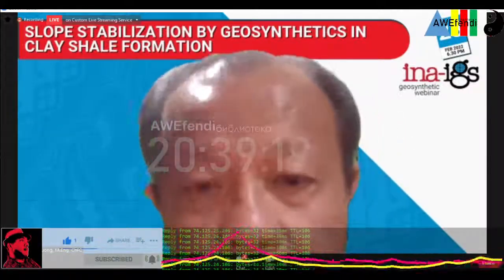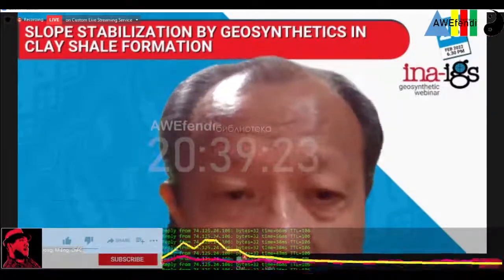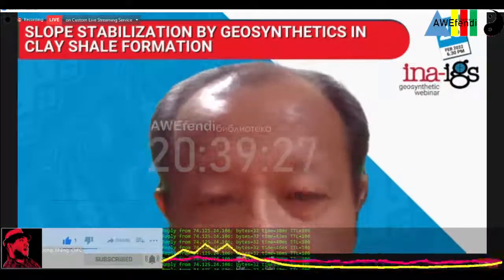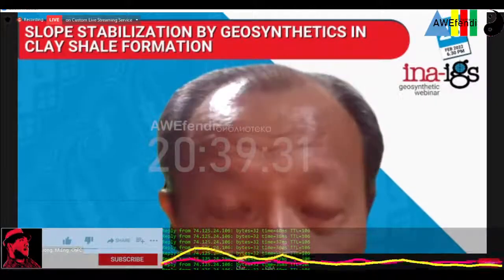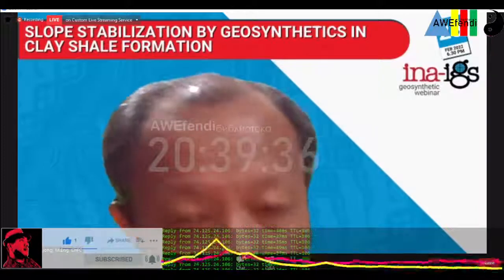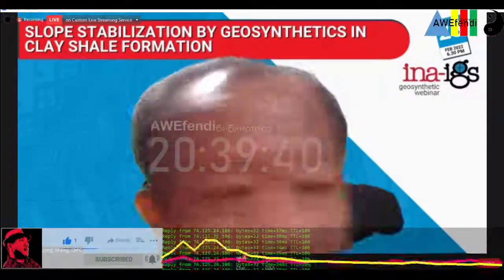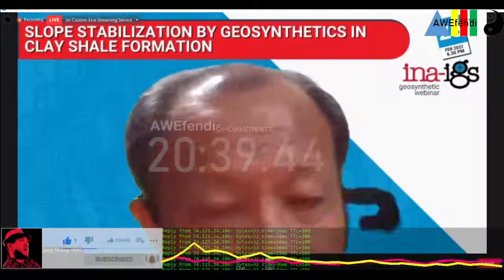Yeah, I do agree that, as we saw during my presentation, we estimate from the Plaxis analysis can be around 50 centimeter movement. So what shear strength do I adopt? When we use the dynamic analysis, we don't take the peak strength. Of course, we don't take the peak strength.